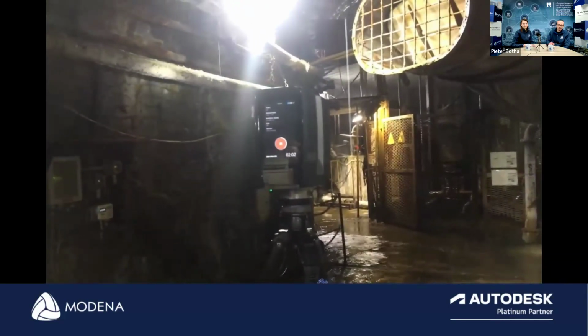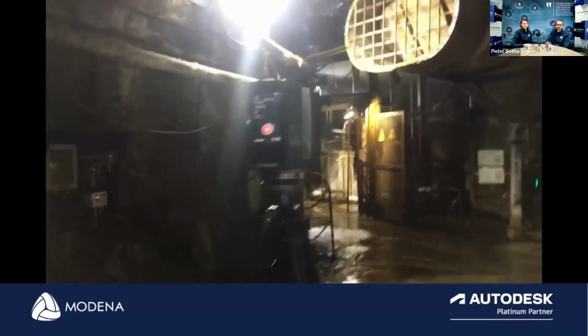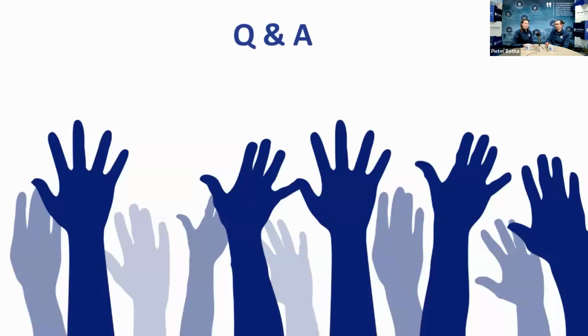Okay, I see we do have a question. If you have a large project or site, do you think survey control is important? Yeah, that's a very good question, and yes, that would be very, very important. You need to establish survey control throughout your sites. It serves as an independent check against your own point cloud data set as well.